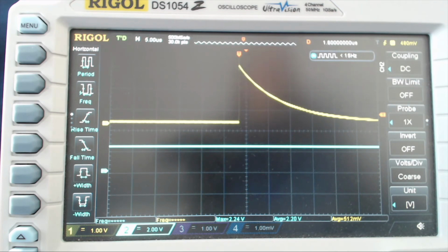Remember that this is a bipolar ADC, so it means that 0 is the level 2048. Above this value we have a positive signal. Below this value we have a negative signal. So how to set the threshold?